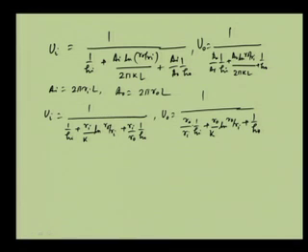We have seen in case of conduction that ln(Ro/Ri) by 2 pi KL becomes the resistance in case of a cylindrical body. So, this is the final expression in terms of radius.